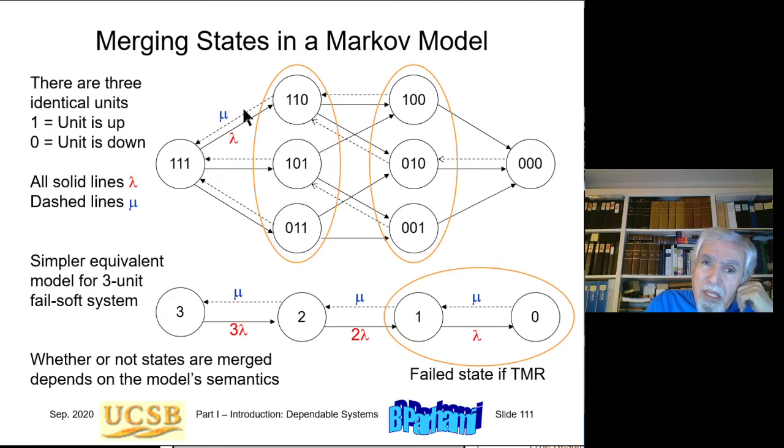Okay, so this rate mu is typically much larger than lambda, so the system is much more likely to be in this state. If it just goes out of that state, it will likely go back to that state quickly and does not spend much time in this failed state, partially failed state. Okay, similarly, we can assign transitions to the other ones. So if all the 3 processors are identical, then I can say, okay, this is also lambda, this is also mu, and so on. In this case, processor 3 has already failed. Processor 2 also fails when we go into this state. So this is still lambda.